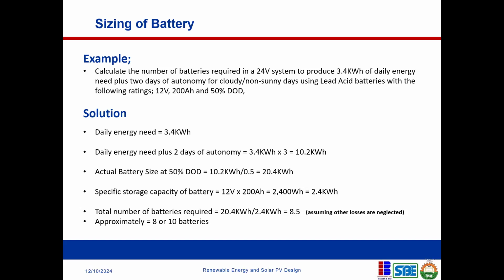So we add batteries in, now the system voltage is 24 volts. This 24 volts is what is going to go into your inverter. So when you're looking at an inverter, you might look at an inverter that accommodates 24 volt input. However, your battery voltage is 12. So to arrive at 24 volts, you need to pair two batteries in parallel. No, sorry, in series. Okay, you need to pair two batteries in series. Correct? Am I right?